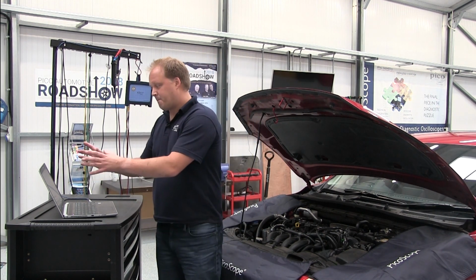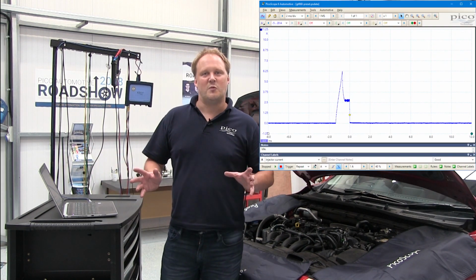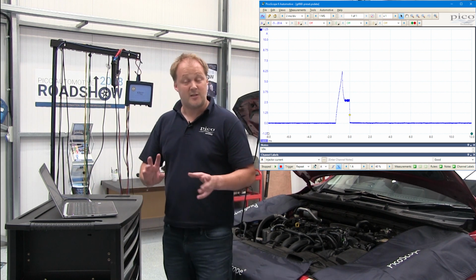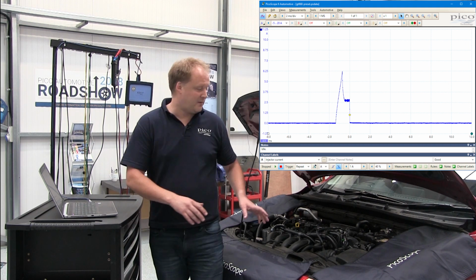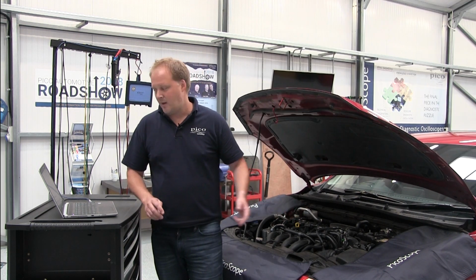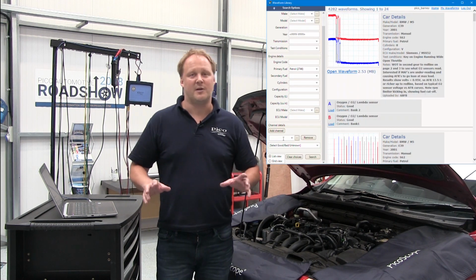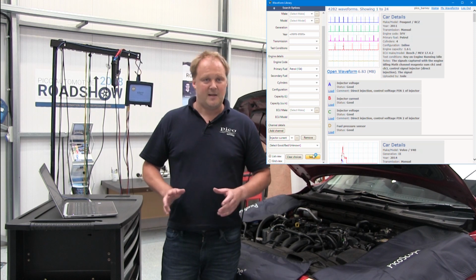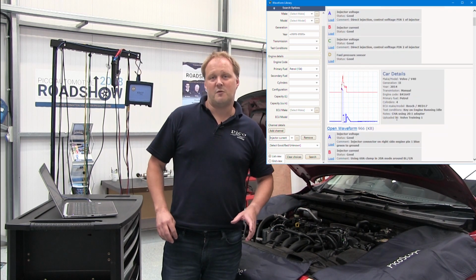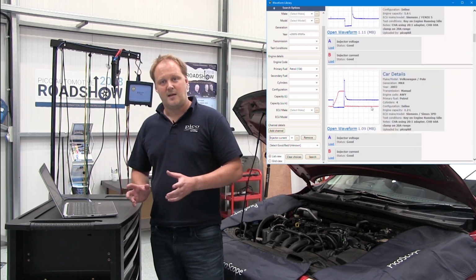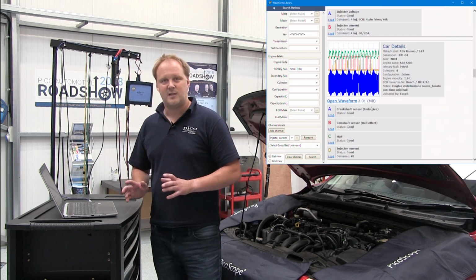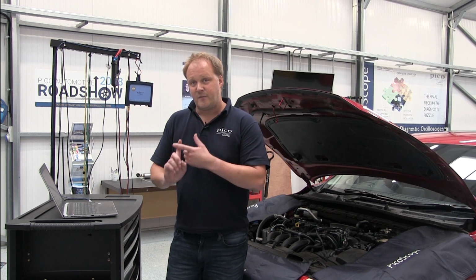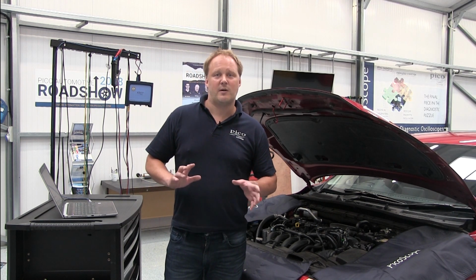Okay, so within the guided test, we've got an example waveform. So we can now compare what we've captured to that example. Does it look the same? Maybe it doesn't. Maybe we've got a different type of vehicle and engine. So we can go to our waveform library, which is made up of contributions from PicoScope users from all around the world, where they've put their injector current waveforms onto it. You can browse through that and see whether your waveform matches any of the good or bad examples in that library. Failing that, you might need a bit more background information.